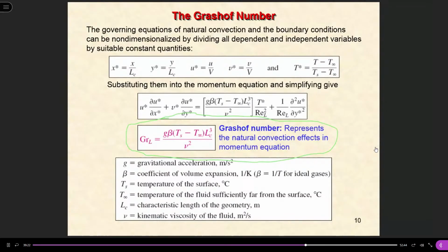Well, we define all the dimensionless, so-called non-dimensionalized variables. We divide the x by a dimension, for example, the height of the wall. We divide all the velocity by a notional velocity. We don't know exactly how large that is, so let's say the reference velocity is v. Then we define a dimensionless temperature. You would find all the fundamental equations can be rewritten as this one.